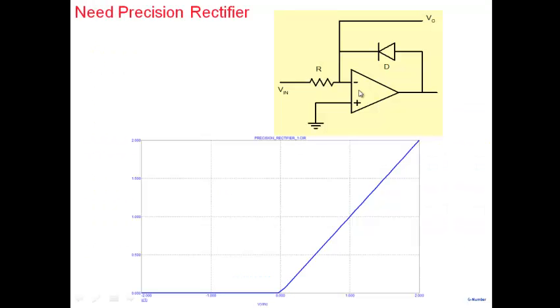All these problems are arising because in this particular circuit, when Vin is positive, the op-amp is in open loop condition, and when Vin is negative, the op-amp is in closed loop condition. This is causing the output to make a large transition from 0.7 to -11 here. So this is causing slew rate problems, and this would prevent our circuit from working at higher frequencies.